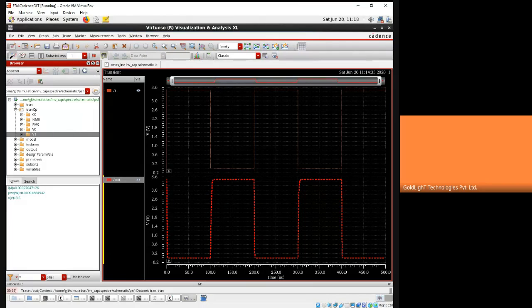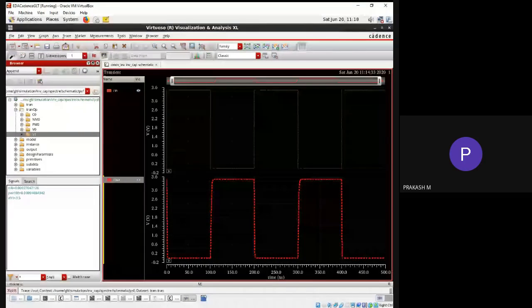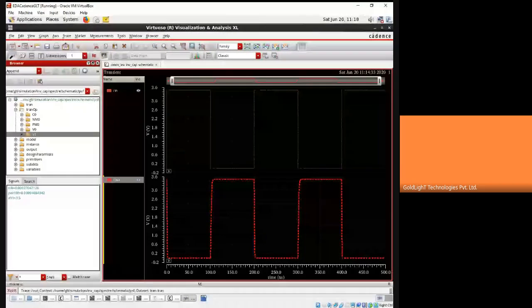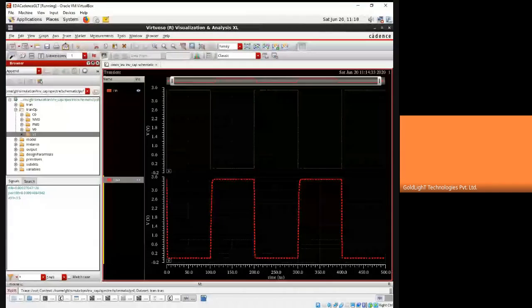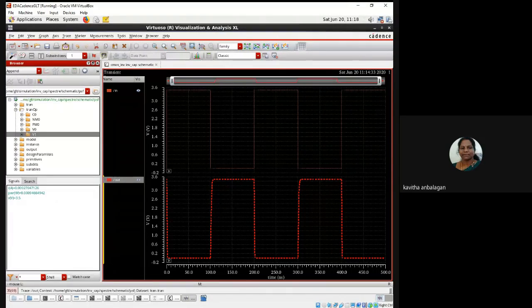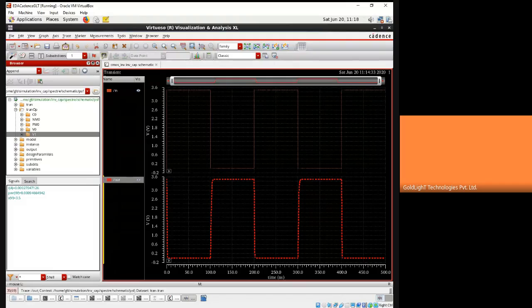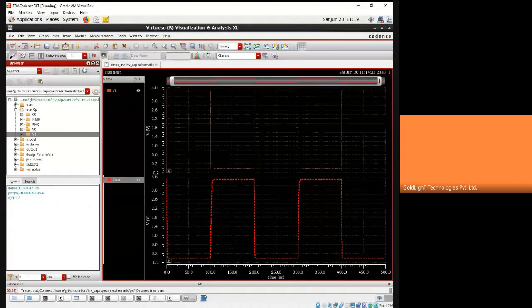Yeah, that is actually based on the design. If I change it, NMOS for 2 and PMOS for 3 by 4th of the ratio of NMOS, is it possible? Yeah, actually, in this design, I have changed it for the NMOS. Actually, I have selected half of that width. So you can change that, but for the half ratio you can get better performance. But for some applications, you have to vary it. For example, if you are going to vary the threshold to 0.5 volt or 0.75 volt, then you can vary that.